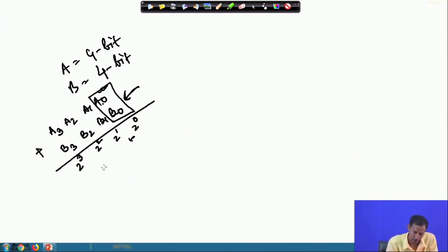Okay. So, that means now for these two particular cases, whenever I consider this bit position, at that time it is not that only A1 and B1 are involved for specifying the sum value at this particular point. Why? Because the carry which is generated from the previous level will also affect the corresponding sum and carry values. So, that is why at that time it will not be a half addition or half adder operation.